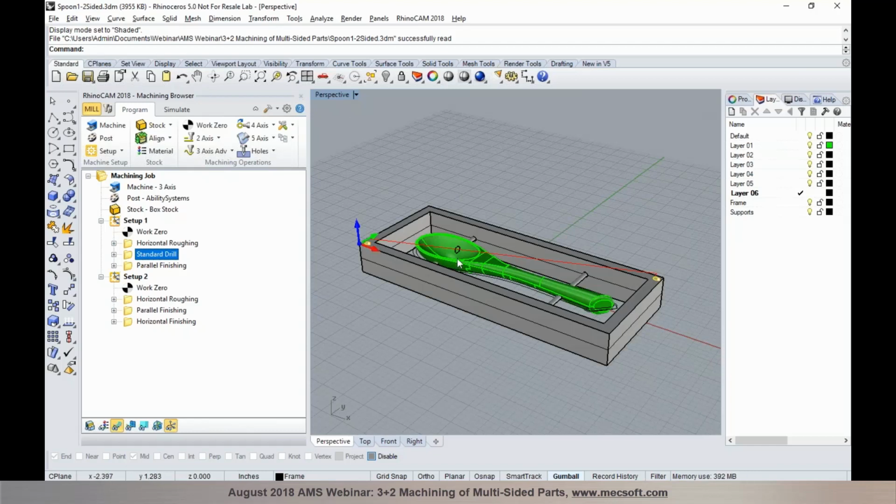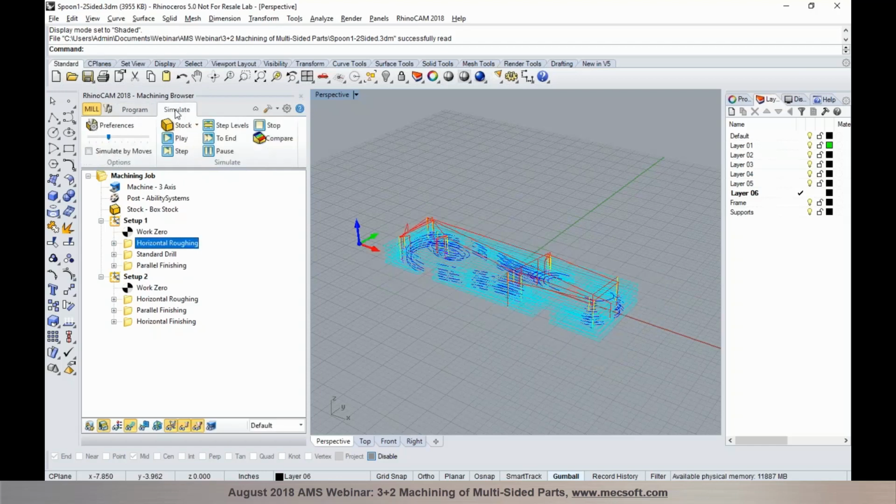So when you flip them over, you can line them up perfectly to the registration hole, so there wouldn't be any offset or shift when you flip the part over as you're programming it from 2 sides by manually flipping the part over. And I also have a finishing operation for side number 1. So let's go ahead and run a quick verification for that.